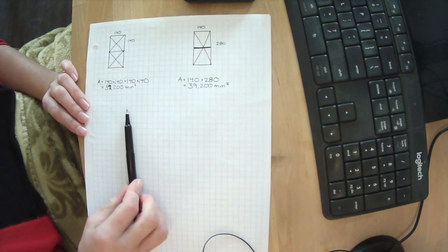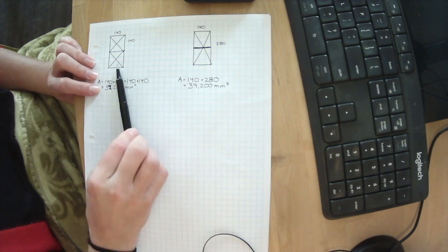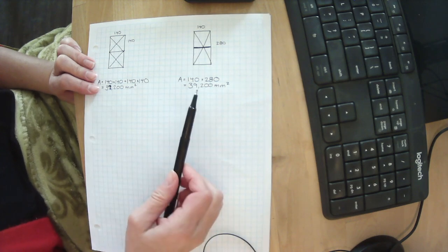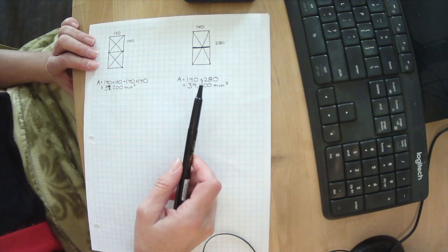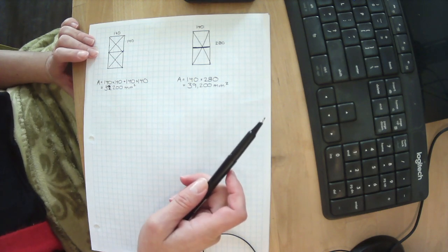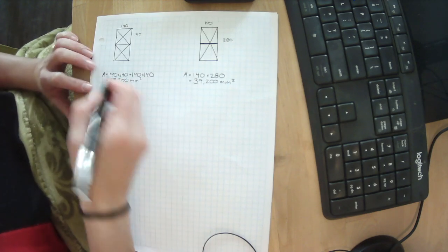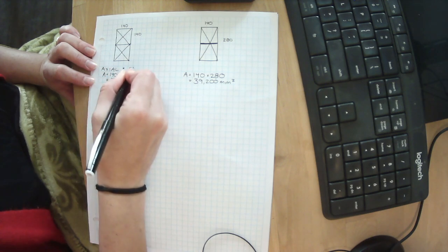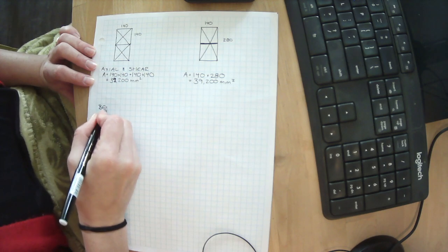is the exact same. If the shape property that we use in shear and axial loads is area, it looks like making it composite or taking the time to glue that together didn't do anything for us. So for axial loads, there's no real advantage to making it composite. For shear loads, there's no huge advantage for making it composite. So this was for axial and shear. Let's look at the bending shape property.